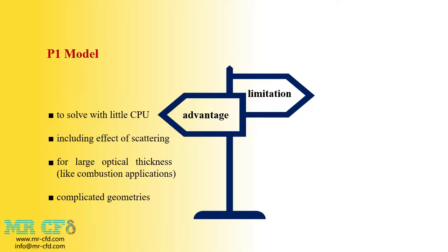The second advantage of this method is that it takes into account the scattering effect. Third, for applications such as combustion where optical thickness is high, this model works relatively well. Fourth, this model can be used for complex geometries with curved coordinates.